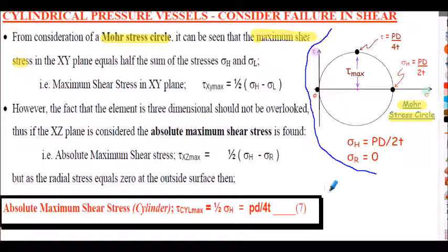If you know your principal stresses, for example, we know that the hoop stress in the vessel is PD upon 2T. We know the value of PD upon 2T. We know the longitudinal stress is actually here. It's half of that direct stress. It's by this position here. And the radial stress we always consider to be zero. Those would be our three stresses.